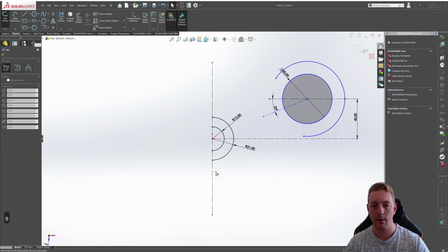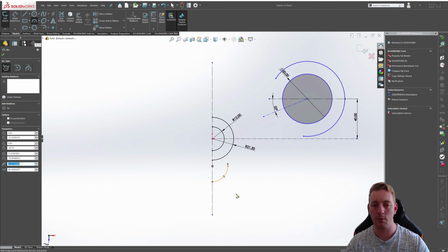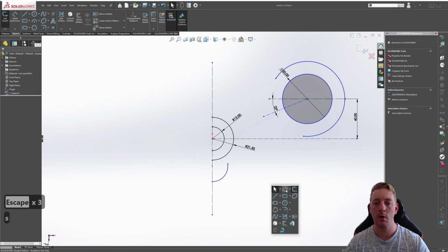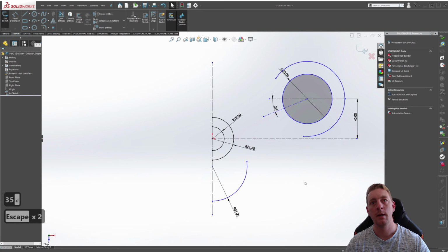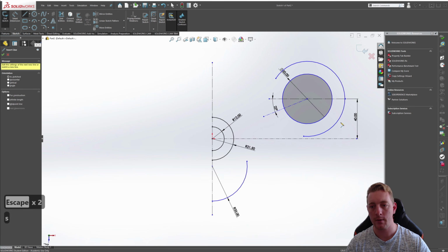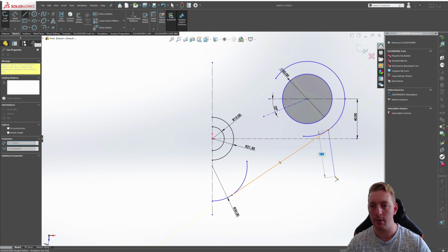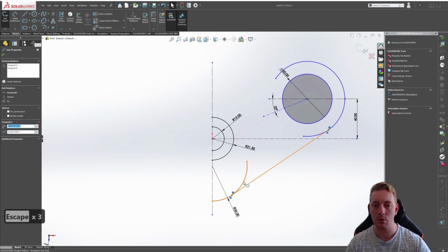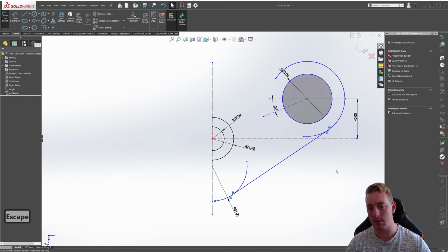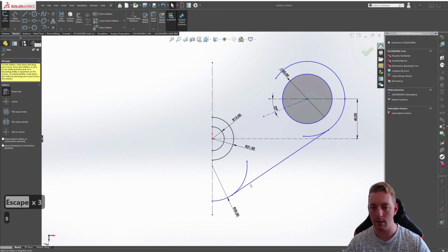We also have another center point arc somewhere here. And the interesting thing about this bottom arc is the center is not at this center point as well. When you finish modeling, it comes down just a little bit. So let's draw this center point arc, say about here. And we're going to over rotate a bit and just put it about there. Now we know our radius for this is 35. And what we want is a line that's going to be tangent between these two. An easy way of doing this is to pick a point on the line and a point on this line, and make sure that there is a tangent there and a tangent there already, so that is done. We can go ahead and trim this back.